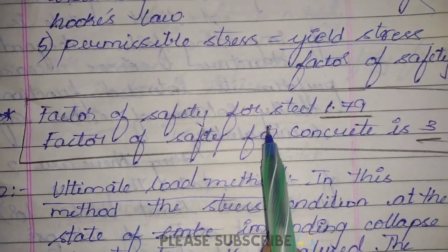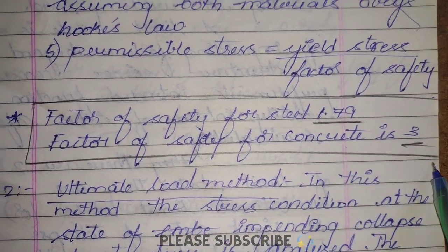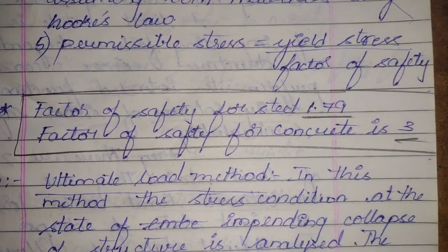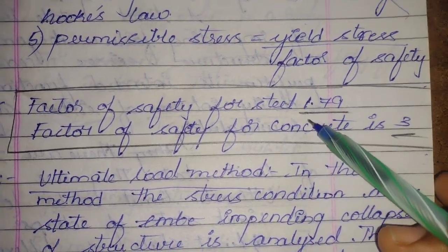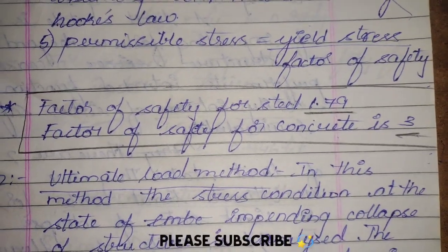And here the factor of safety for steel is 1.79. The factor of safety for concrete is 3. It is a very important question that can be asked in any competitive exam, guys. Remember, under the working stress method, whenever we are asked about the factor of safety of steel and concrete, the values would be 1.79 and 3 for steel and concrete respectively.